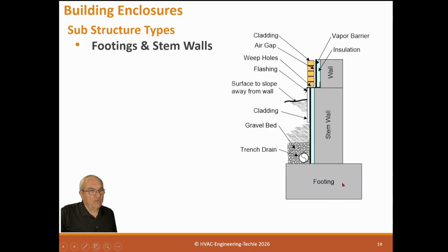This is the footing for a wall, and this is the device that provides the support of the building by the area of this bottom foot here. It also helps with the uplift of the building because it's covered with earth here, or compact material. This is a stem wall, and this is what carries the load from the actual building wall back down to the footing. It's called a stem wall.